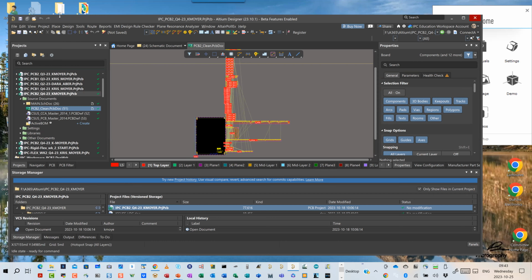Decrease in surface insulation resistance, no ionic contaminants left. Not only are you telling them to wash it, you are telling them what level of cleanliness you expect of your board after the fact. So those are notes we're going to put on the assembly drawing.